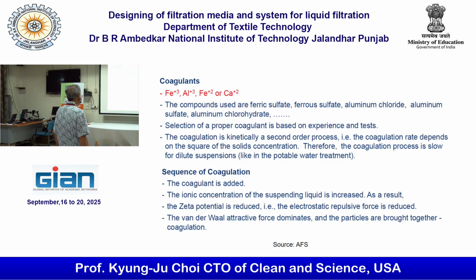Coagulation is kinetically a second order process. The coagulation rate depends on the square of the solid concentration. It's slow in dilute suspensions like potable water treatment. Somehow you have to reduce the zeta potential in order to make the particles overlap. That's the conclusion.